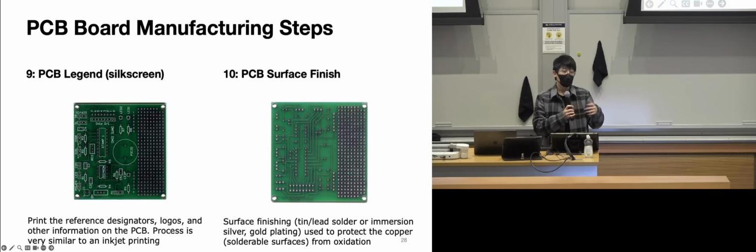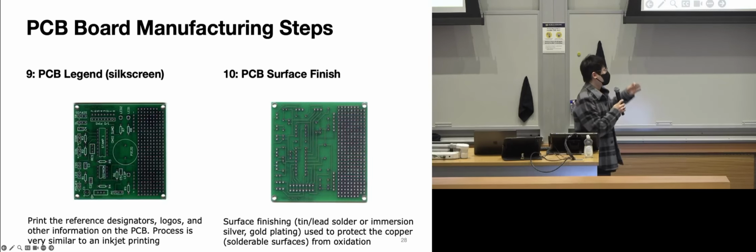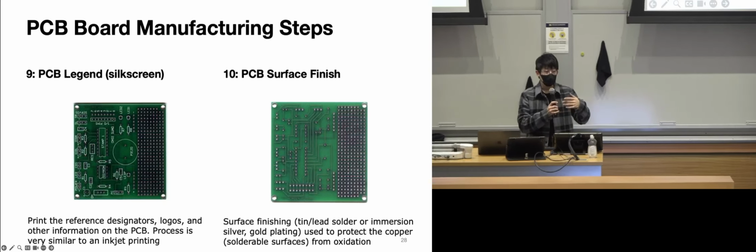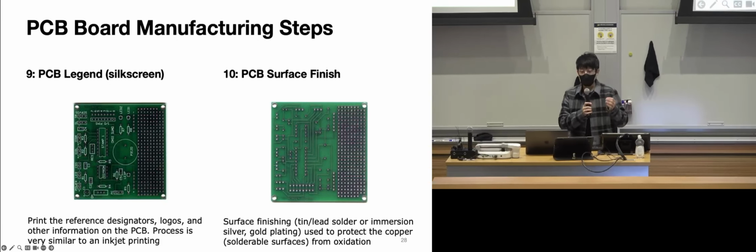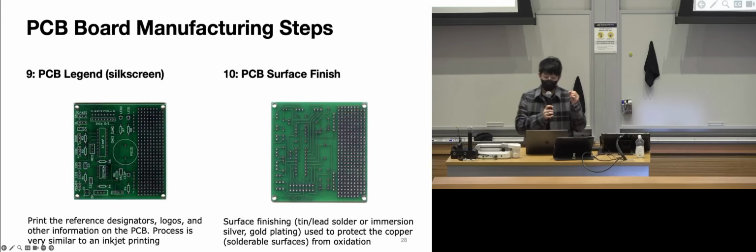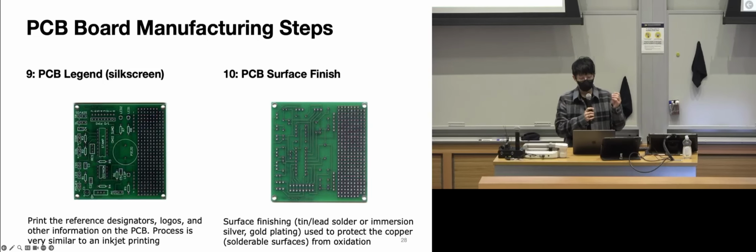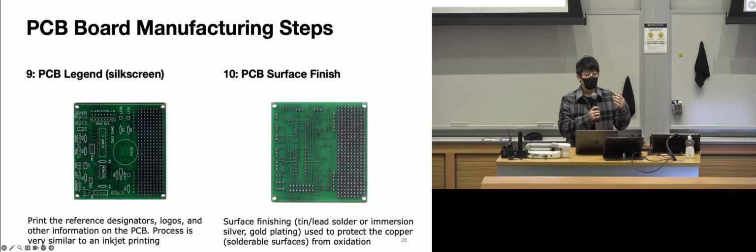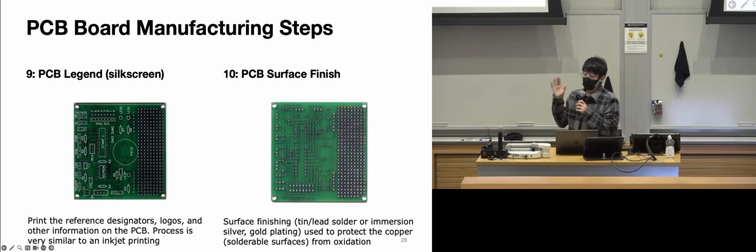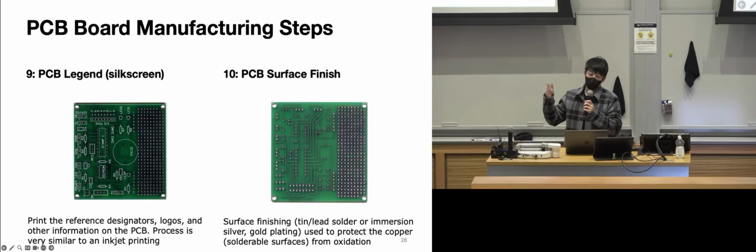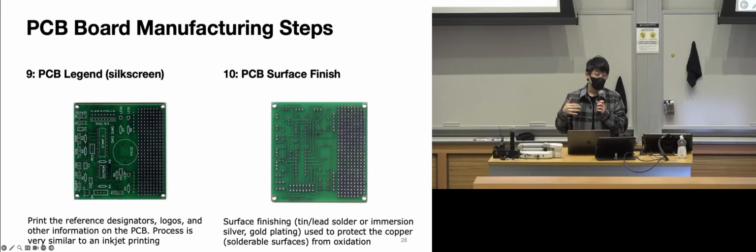If it's a capacitor, it's C1, C2, and if it's a jumper or connector type, it's usually JP1, JP2, etc. This is so that engineers or programs later will know what this component is and have a good correspondence from the manufactured PCB to the schematic or circuit diagram. Essentially, it tells you what this board is doing and how you are supposed to interact with it.